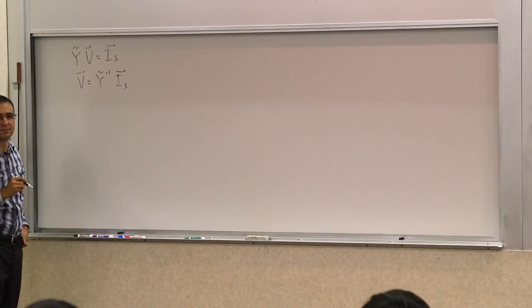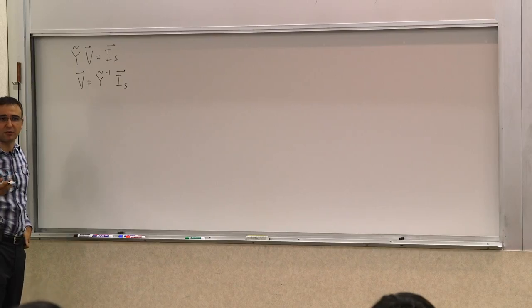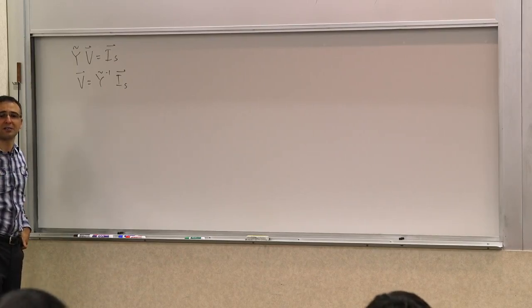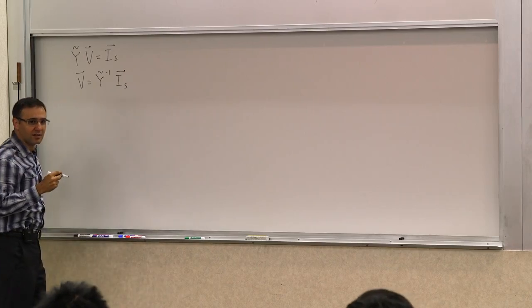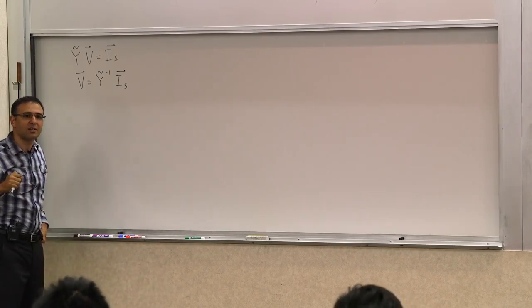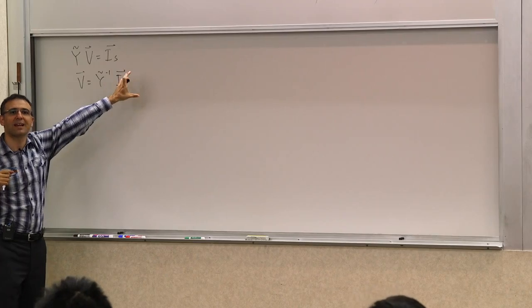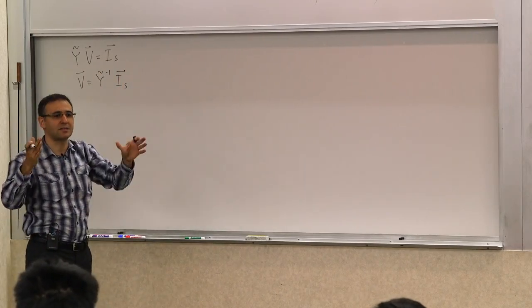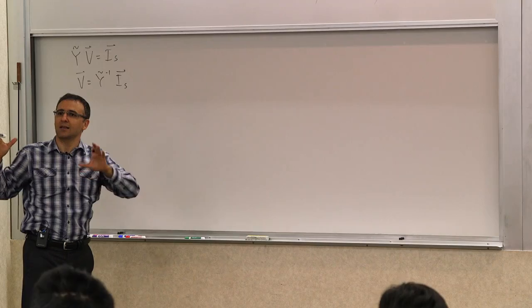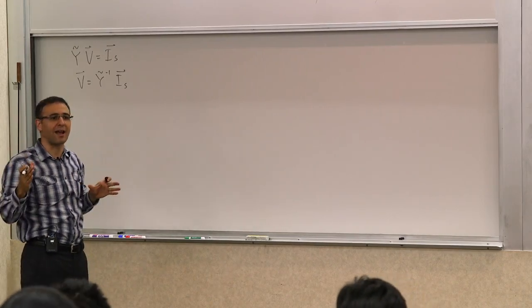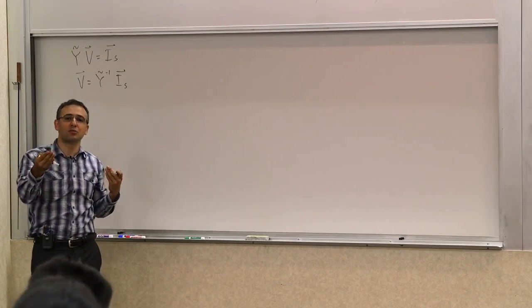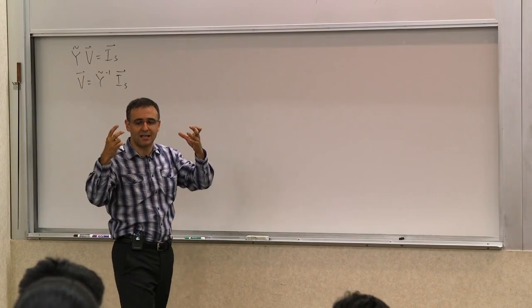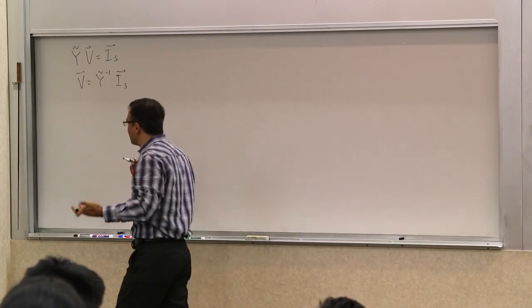Yes? When Y is non-singular. When Y is non-singular, when you can invert it, which basically means, another way to say it, what can you say about it in terms of its determinant? The determinant is non-zero, right? So if you have a determinant that's non-zero, you can basically invert it. This is a mathematical thing. Can we translate it to a circuit characteristic, something where we can look at a circuit and say this circuit does have a solution or does not have a solution? This is where the Y matrix analysis formulation comes into use, because you can think about these inverses as entities and play with them and come up with results.